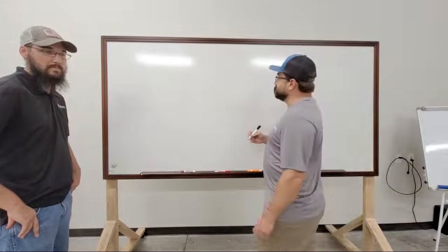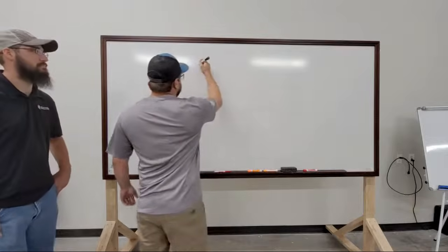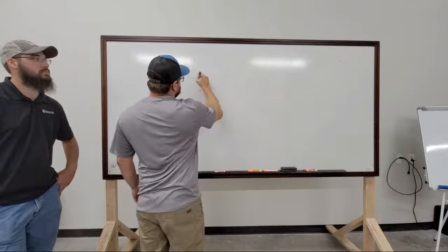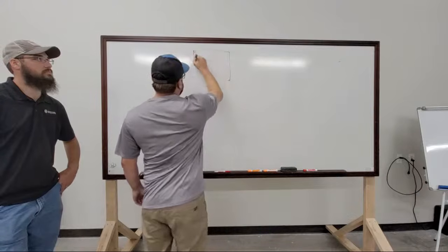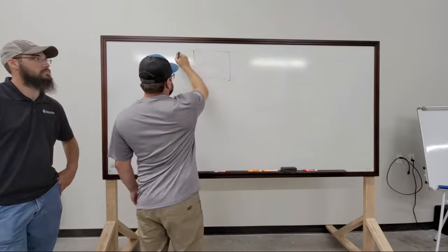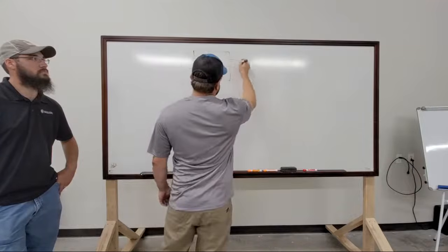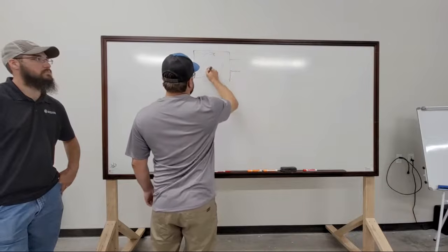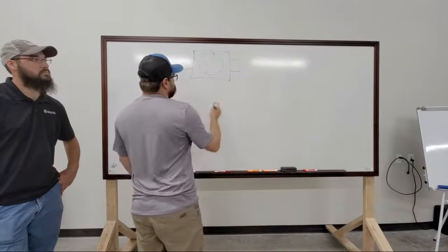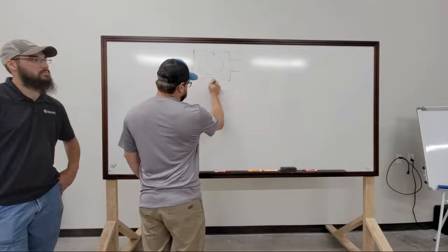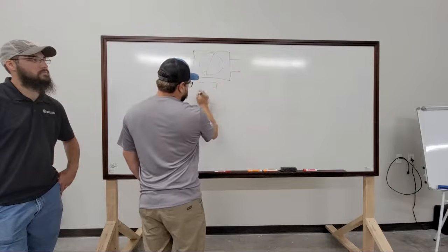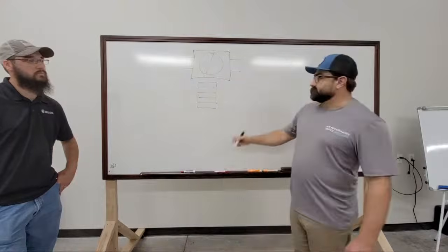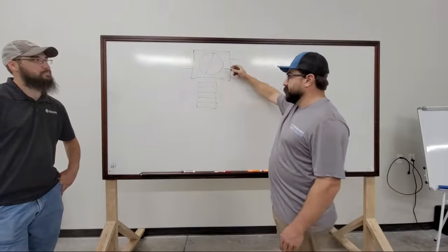We'll start with VAVs. There are two main types of VAV boxes in a variable volume system. First is a normal, single duct, has a damper in it, either a round or a square damper with an actuator on it that is going to modulate the amount of air going through the box.